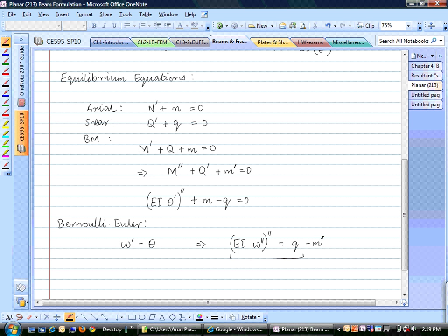Yeah. So basically, this is the equation for two-dimensional beam theory, and we'll first try to study it. Now, this is a one-dimensional equation. The only variable here is x, and the only unknown here is w, the transverse displacement. So that complicated three-dimensional beam, right now we are studying only with a two-dimensional beam theory. If we can somehow find w, the problem is done.